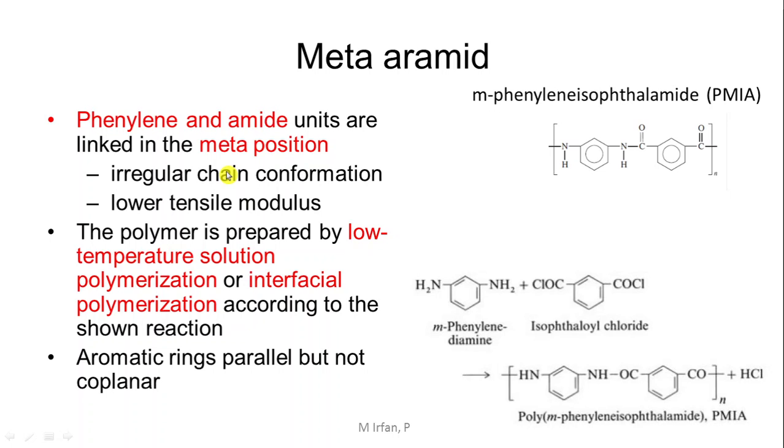In meta-aramids, phenylenediamine and amide units are linked in meta position, which results in irregular chain conformation and comparatively low tensile modulus or tensile properties compared with para-aramids.